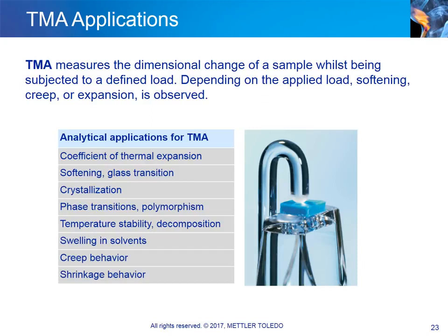Besides conventional TMA measurements, in which the load remains constant, dynamic load TMA or DLTMA can also be performed. This mode typically employs a periodic applied load with a constant amplitude, for example, plus and minus 1 Newton. If a sample hardens, as in the cure process, the measured displacement amplitude decreases markedly. This technique can be used to determine Young's modulus.